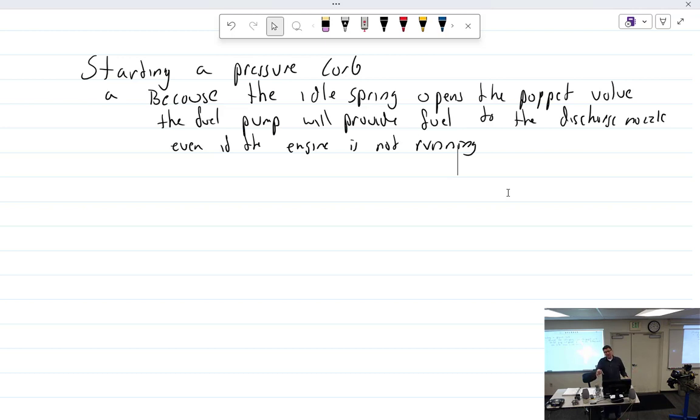Maybe I was a little too flooded. That adds air. If that doesn't do it, I'll bring it back. If that doesn't do it, I'll start to bring the mixture up a little bit. But usually it catches at that point. At that point, you've got to bring the mixture back. Mixture forward, throttle back. So you've got start, mixture.